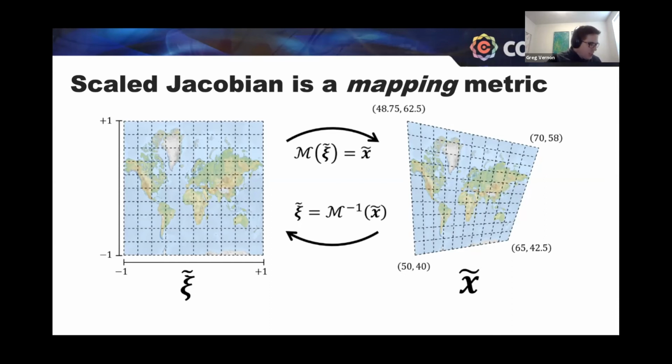But then what I will say is that, in my opinion, the best metric for how good my mesh is, is how good my results are. And at the end of the day, that's really all that matters, right? You can look at all these different metrics, but if you have results that don't make sense, then your mesh isn't very good. And so really the best metric is how good my solution results are. And so you still have to consider verification and validation in your simulation processes. It's not just enough to say I have a good quality mesh based on these metrics. You still have to do V and V.